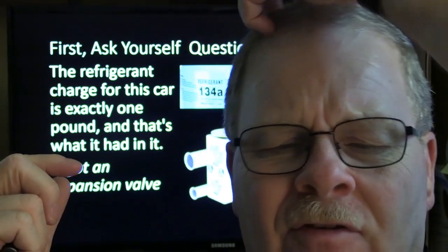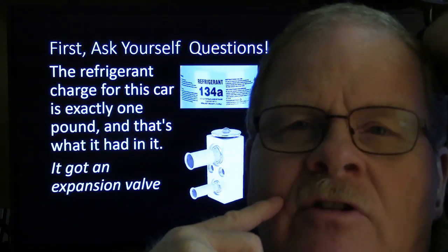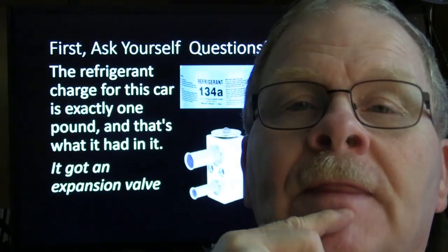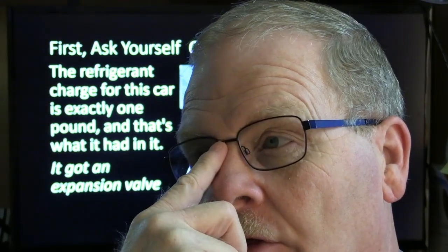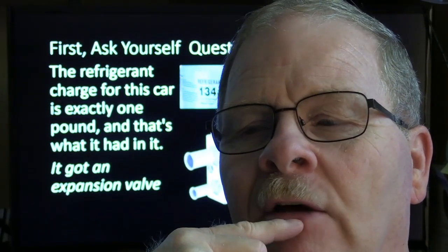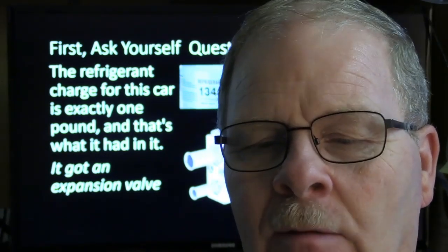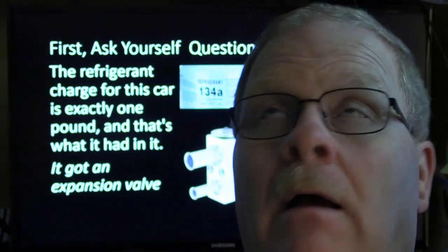Sometimes the expansion valve, you might remember this Ford Edge. It was a 2012 Ford Edge that we worked on, it would cool for about 30 minutes driving down the road, and then it would quit cooling. And she went to the Ford place somewhere, and they told her it needed everything that was under the dash because the actuators weren't communicating on the bus, all that kind of stuff.